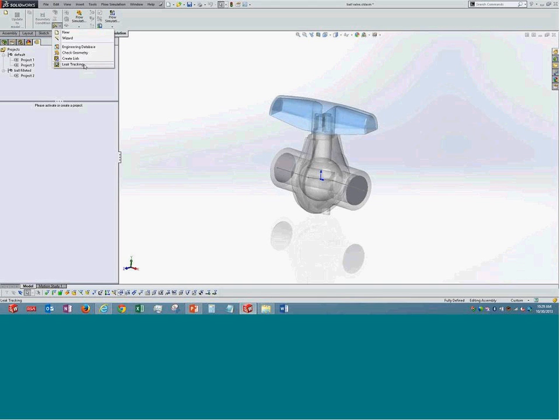If it is a complex geometry and you are not able to understand where lids need to be created, then you can use this option of leak tracking. It helps find the locations where the lids have not yet been created. For simple geometry it is easy, however if it is a complex one, then you might want to use this to understand how to create those particular lids or the location where they have to be created. I will show how it works. If you can see here, it is asking for the start face.